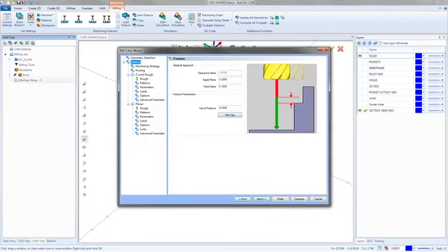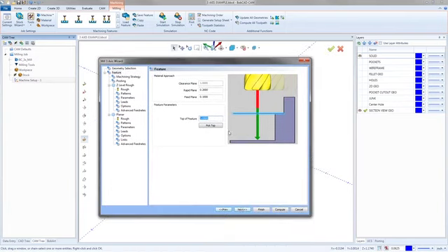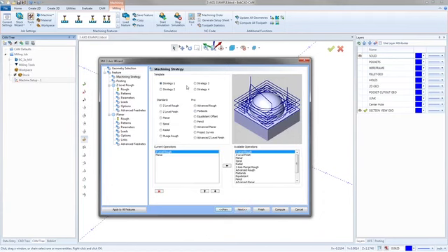I'm going to just drag a box over the whole part and then right click and hit OK and then hit next. Now, top of features, 50,000, that's what I got set for that top. That's actually, I think, that little lip there. So I may not have gotten my origin in the right place. Next, okay, we get to the machining strategy.